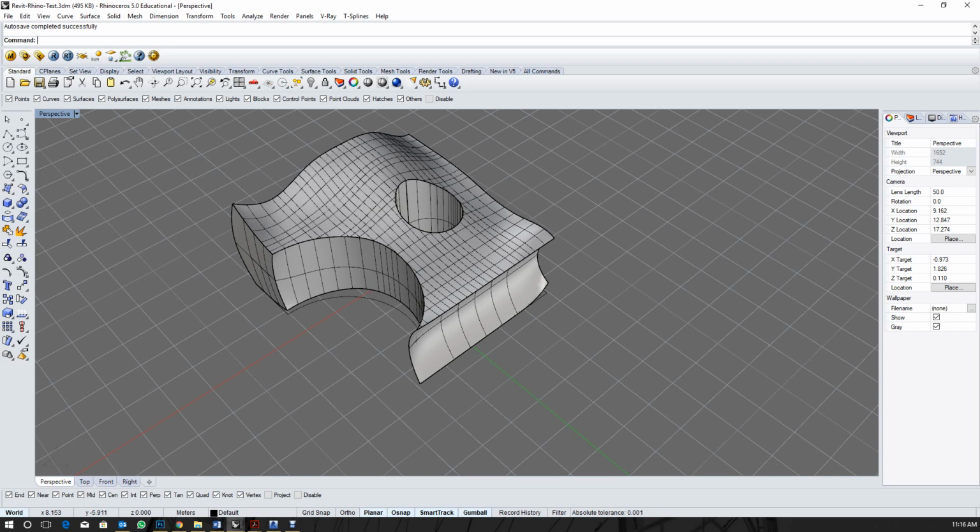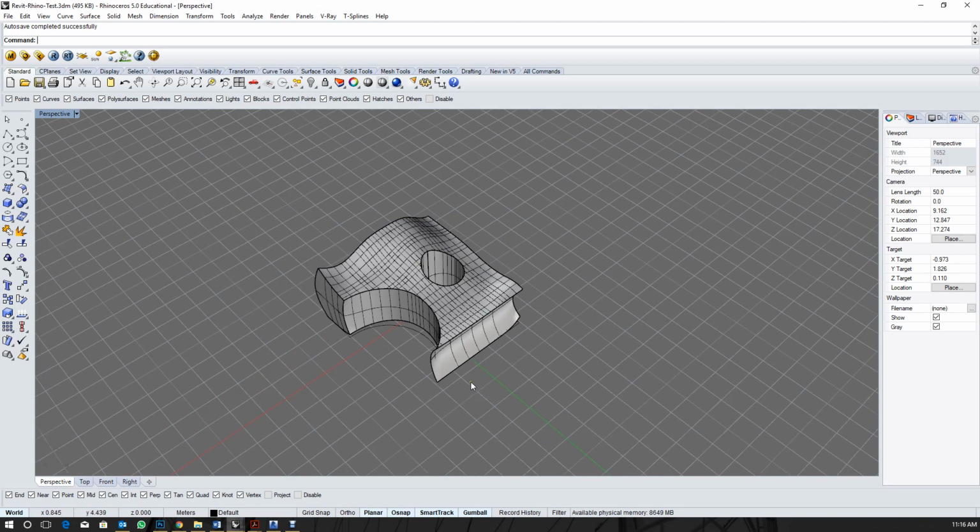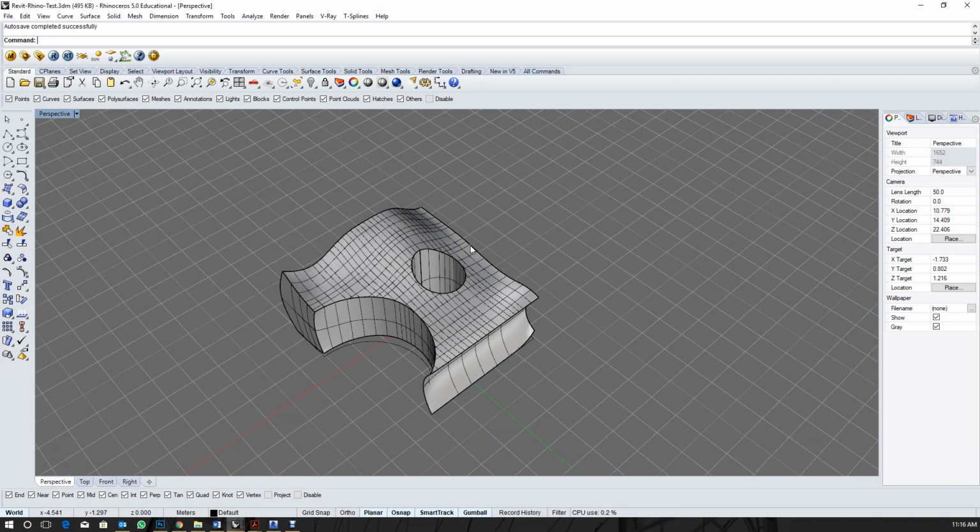The best that I found is SAT, which is an ASCII format, and that works really well in Revit because it exports as a NURB. But you can also export as a DWG, you can export as a DXF, and you can export as a SketchUp. SketchUp is the most useless, let's just put it that way. And you would see why.